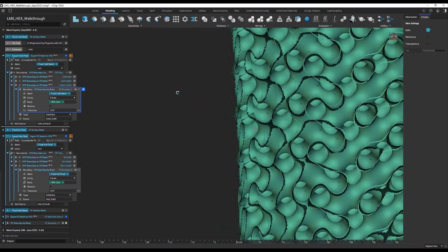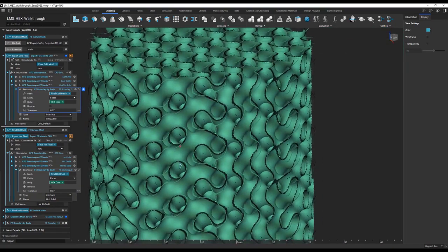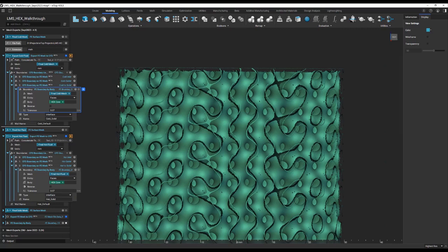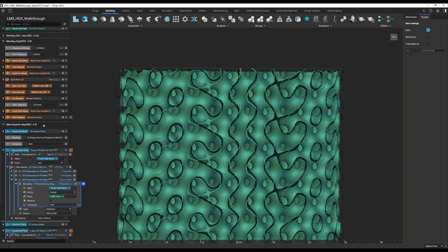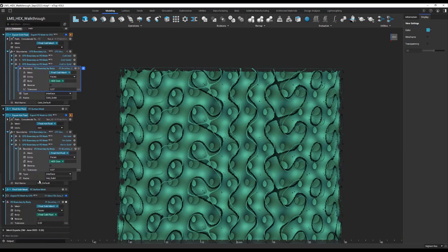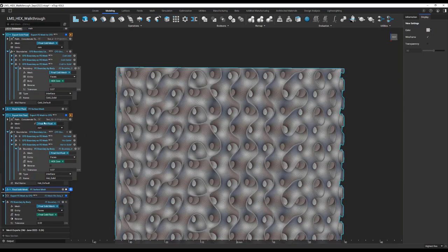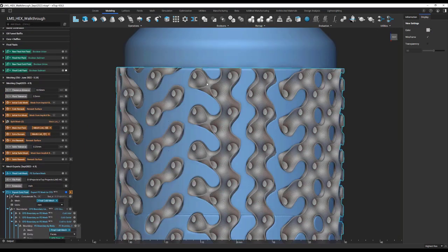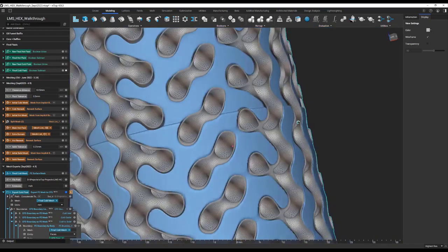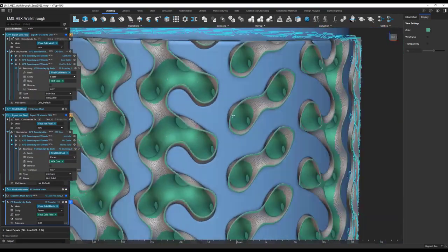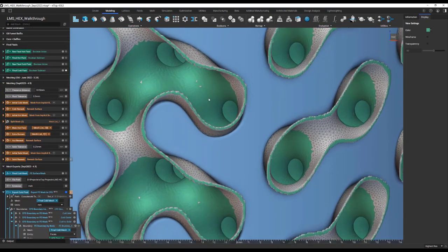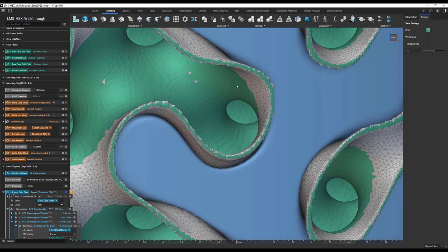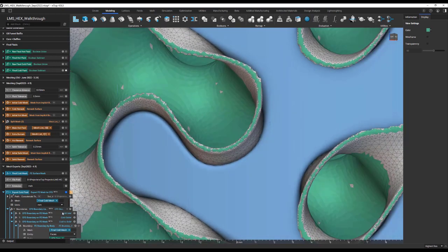Now, one thing I'm not a huge fan of on this interface are the floating bits. Let's see if we can resolve why that's happening. Final cold fluid is our selection body, and that's probably the culprit. So we'll turn on the mesh, look at the final cold fluid, and we'll actually see that we're capturing beyond that as well.